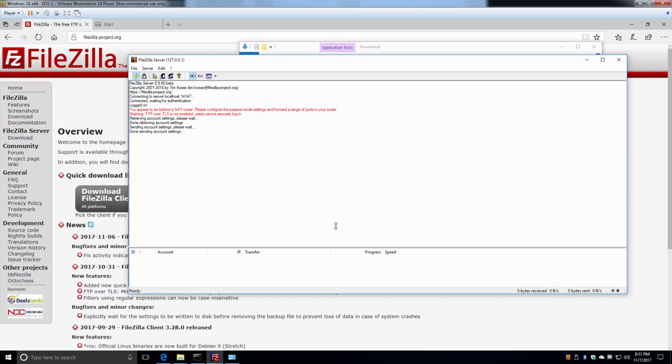So now at the nanodac, I know you can't see this, but I'm going to go ahead and log in as supervisor. I'm just going to do a demand archive. Type in my default password of 100. Accept. I'm going to go down to demand archiving. When you go to demand archiving, you can choose what you want to archive to where, whether it's the USB stick or your FTP server. I'm going to go ahead and click FTP server and archive the last hour.